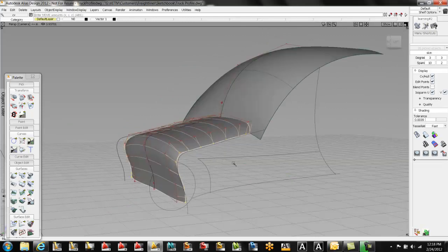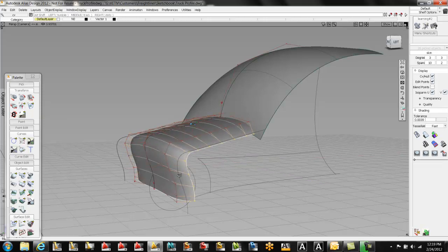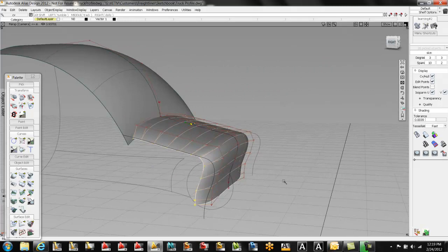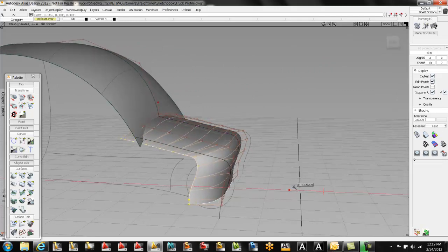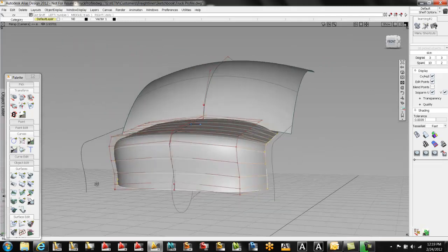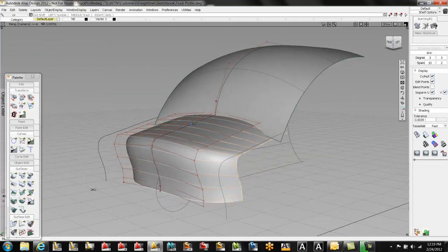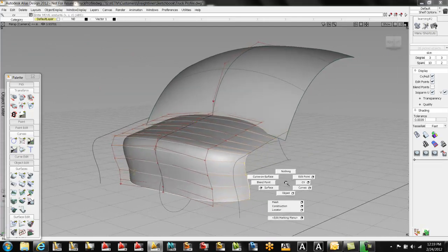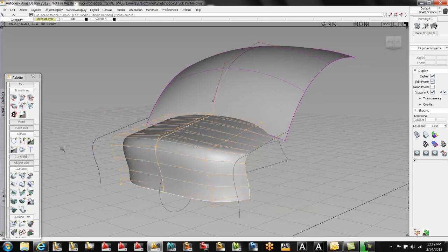So the idea, again, was with that Falcon tool, I can see how that surface area is contacted by my wind tunnel, what kind of turbulence, what kind of velocities I can bring up there, and that can quickly give me some initial concept designs before I go through and make all my surfaces or go into the detail of my surfaces.